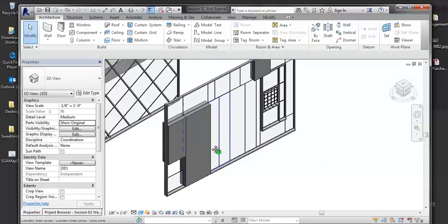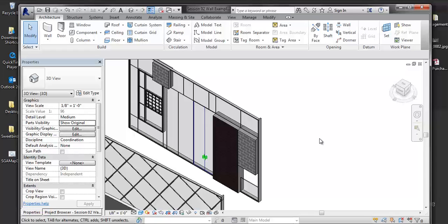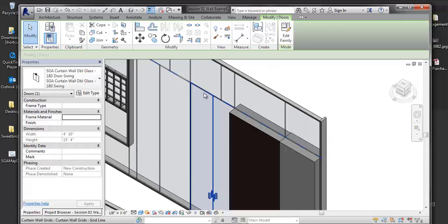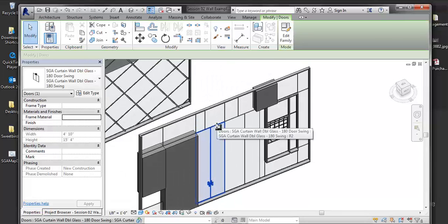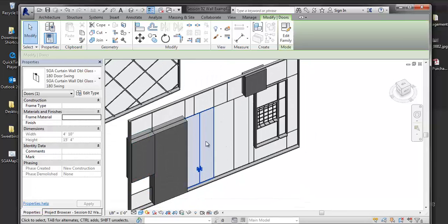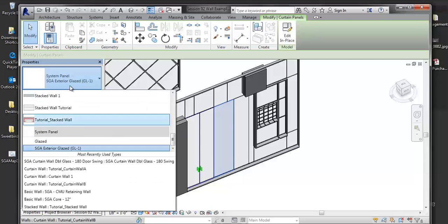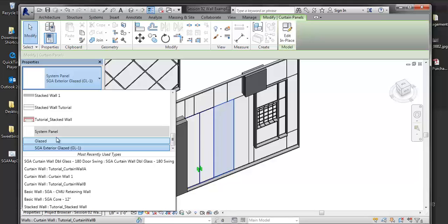Okay. Notice your curtain wall door family is driven by the grids, in the same way as the other panel. It's just driven by the grid separation. So if you wanted a 7-foot high door, you have to drop a grid at that height. So what I need to do to access that, just like we loaded other panels, is I select my panel, and then it's loaded as if it were a wall or a panel. So it's a panel within the family.